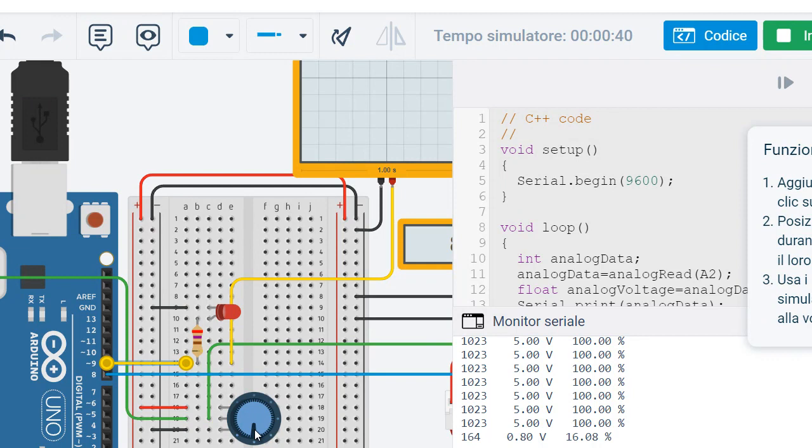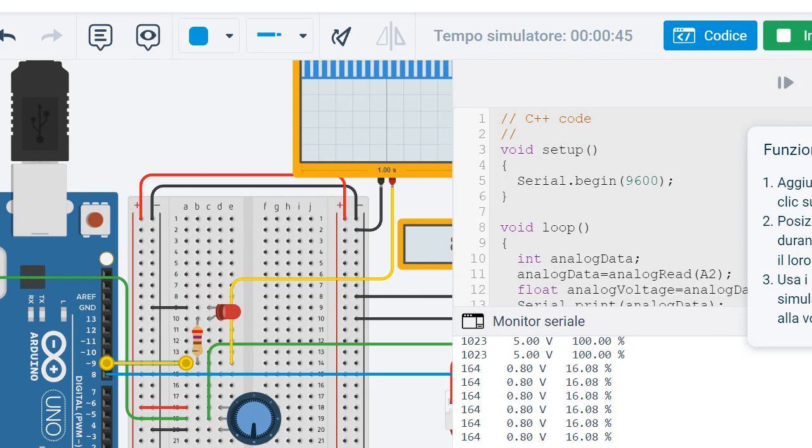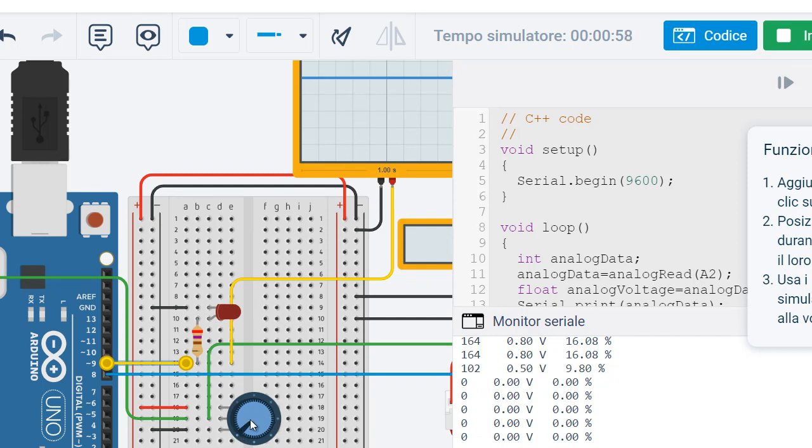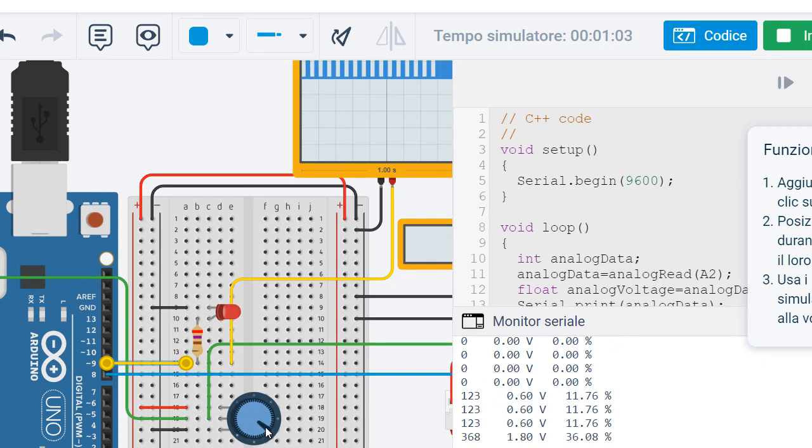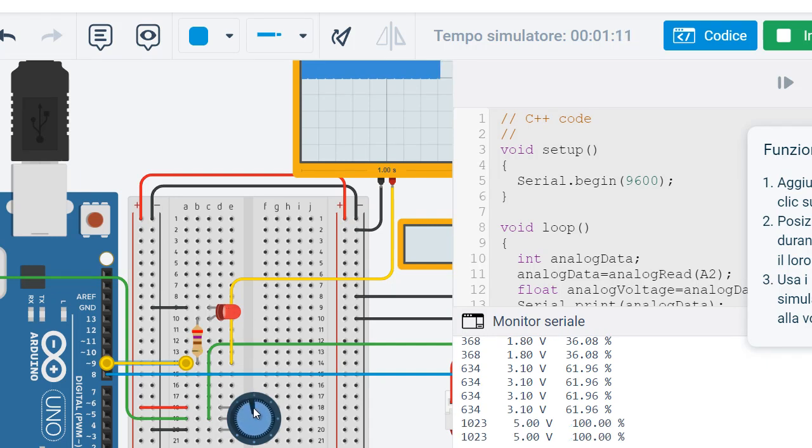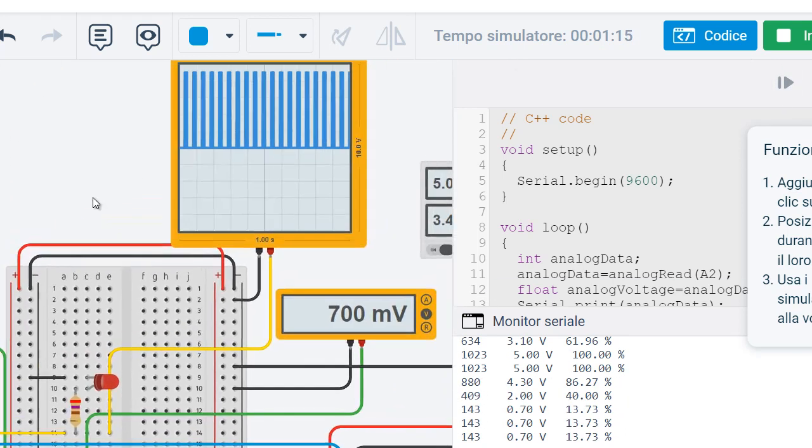And we see here lower light because we now have just a 6% duty cycle, so the LED is less bright. And if we want to turn it off, it is sufficient to have 0 volt with the trimmer, so we can regulate the duty cycle with the potentiometer of the PWM, so we regulate the brightness of the light with the potentiometer. This is a technique called PWM.